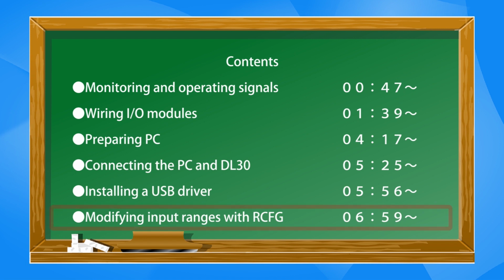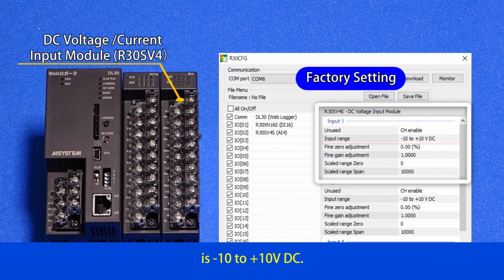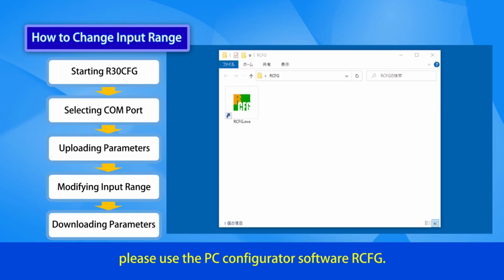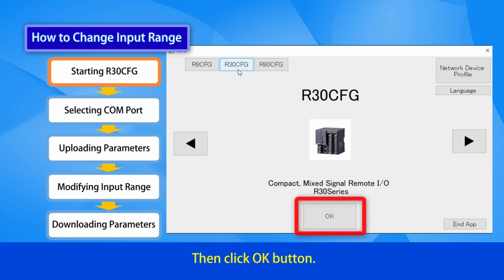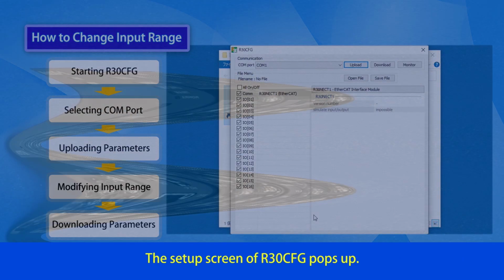In the last step, let's set the input ranges using RCFG. The factory setting of the DC voltage current input module is -10 to +10 volt DC. To change the input range to 4 to 20 mA DC, please use the PC configurator software RCFG. Select the remote I/O series that you would like to use and select R30 CFG. Then click OK button. The setup screen of R30 CFG pops up.